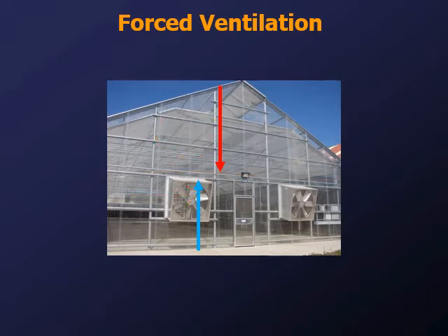There's two schools of thought on this. If you leave this part alone, you're at least managing the thermocline where the plants are, but more often than not, a higher fan or a combination of the two, where one is located up above the energy curtain in combination with below, is a better idea. So we want to think about it from a vertical perspective, because remember, hot air rises and cold air drops.